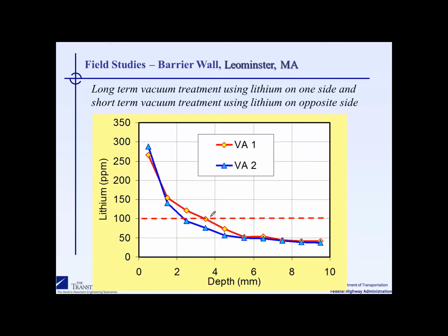And the challenge here is if the pores are already saturated with water, it's virtually impossible to drive any liquid that will displace the moisture in the concrete already. And it's generally not feasible in field structures to dry the concrete adequately enough so that it will be more amenable to receiving the liquid through a vacuum technique. So we'll come back to some additional vacuum trials in just a minute.